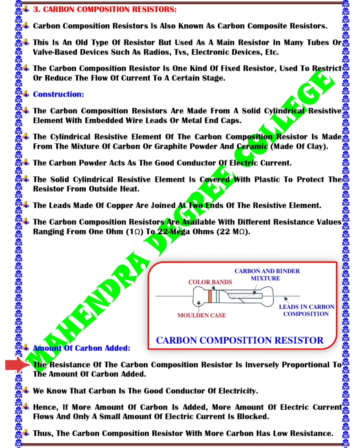Carbon is a good conductor of electricity, meaning it allows current to flow relatively easily. A binder material, like a plastic resin or clay, is mixed with the carbon powder to hold it together and allow for molding into the desired shape. By adjusting the ratio of carbon to binder, the overall resistance of the resistor can be controlled.